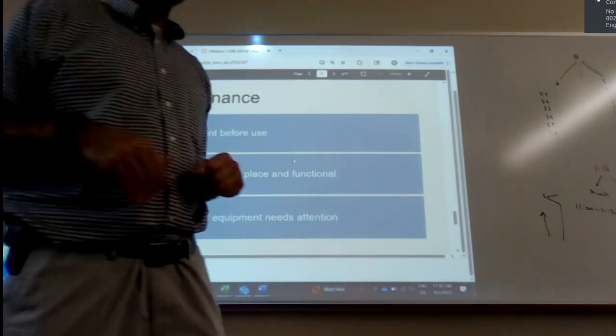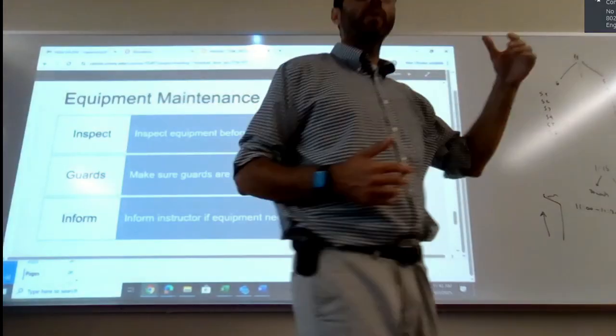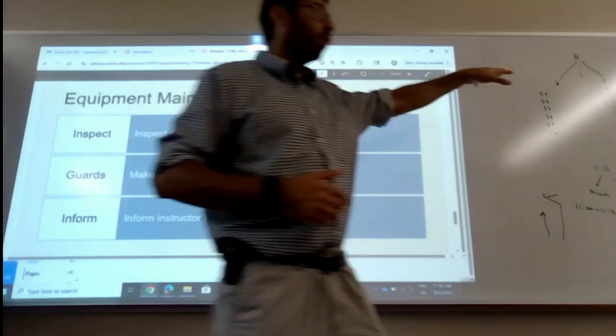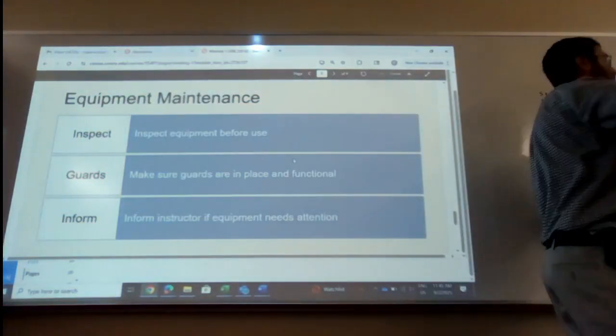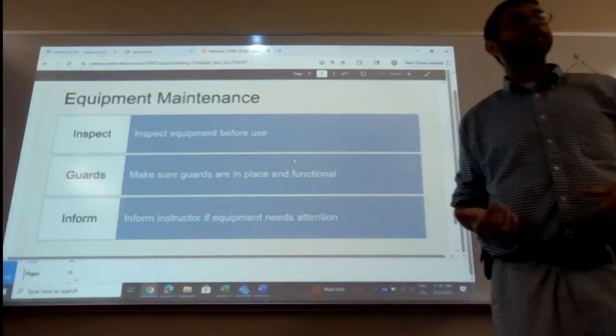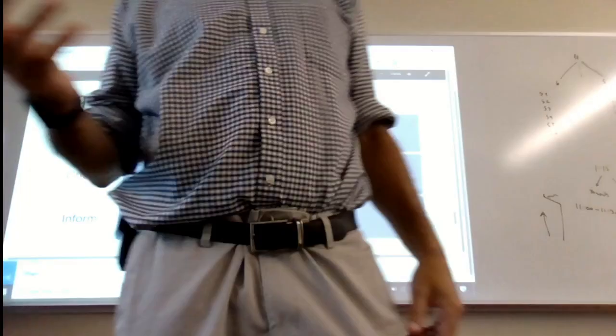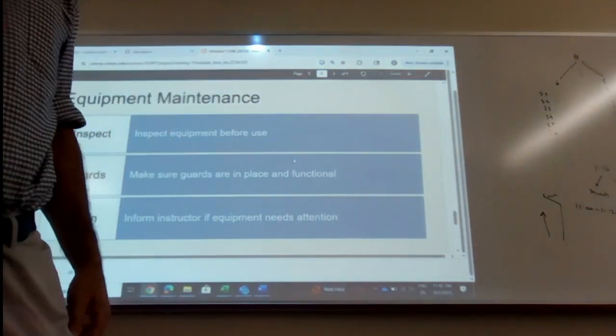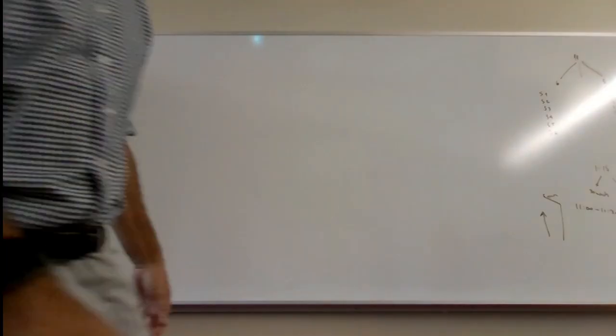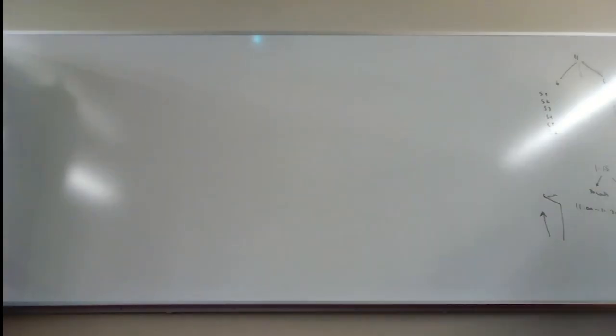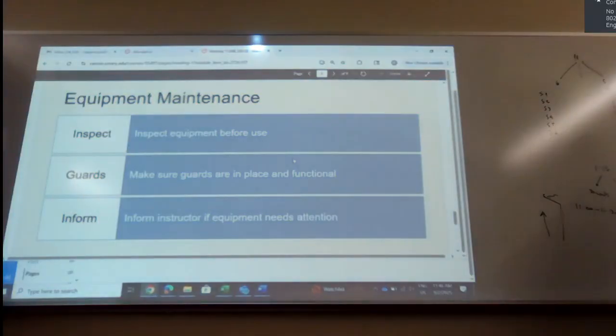You consider anything can be hot in here. So, oh, I'm going to go to the restroom, quick. You go and you stop and talk to somebody in the hall, and then you come back. Is the equipment cold or hot? I don't know, what if Rodrigo did some welding in between? You know what I mean? You have to consider that it's hot. You go in there, you consider it's hot.